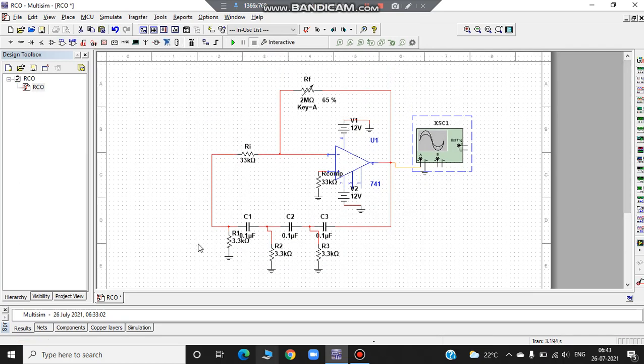So this is an RC oscillator circuit. This is the amplifier block which produces 180-degree phase shift, and this is the feedback block which produces 180-degree further phase shift. So feedback block is made up of the ladder circuit, that is capacitor and resistor, 3 capacitors and 3 resistors. So one set produces 60-degree phase shift, and this next set produces 60, and this next set produces again 60-degree. So totally it produces 180-degree. And this 180-degree and the amplifier's 180-degree phase shift totally produces 0-degree phase shift of the 360, which cancels out the negative things, and